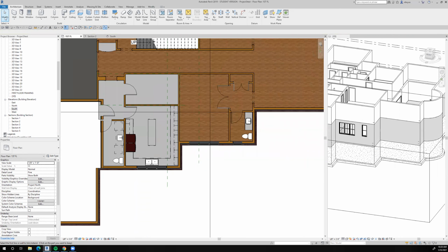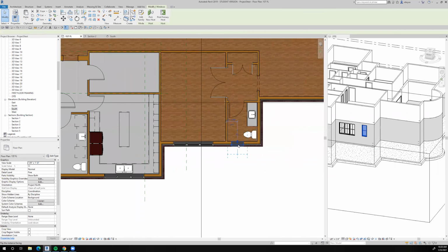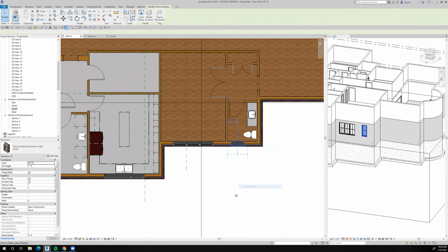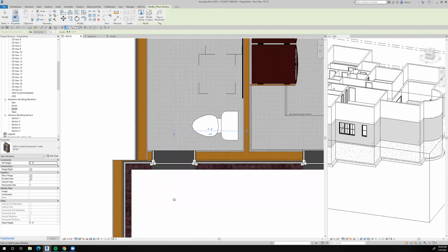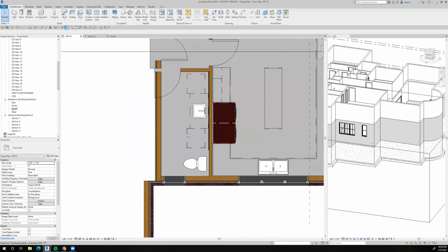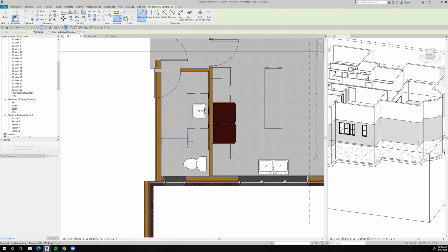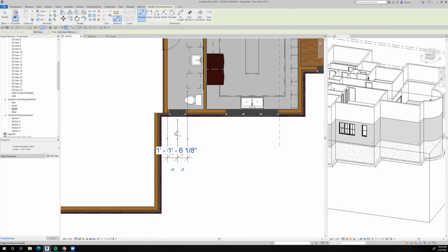So let's try create similar. I think it's a great tool for Revit, and do the same thing. I've got my 4-inch offset. I like that. And again, I've got my, so we can't see the countertop here, but let's say I'm going to do my dimension from here. That is the countertop. And then I'll come back and find the midpoint and say equal.